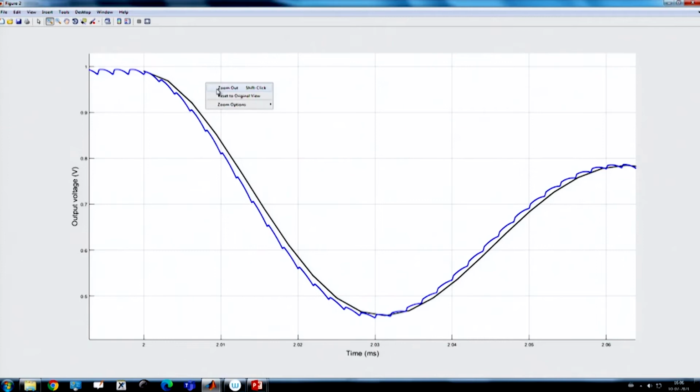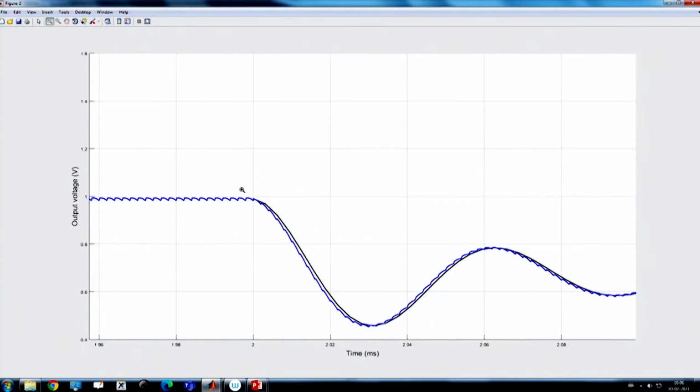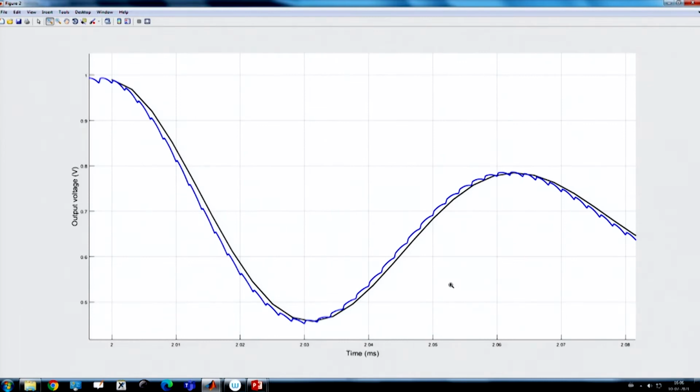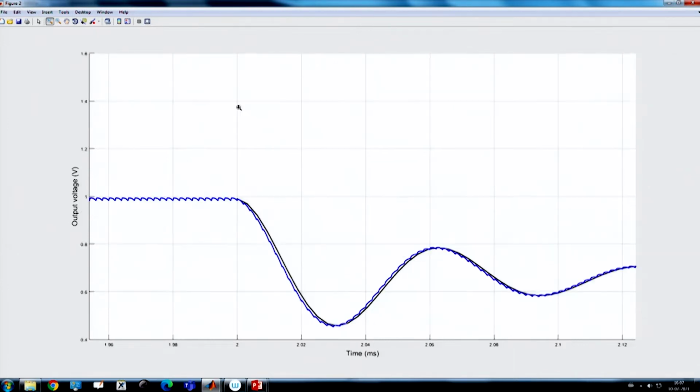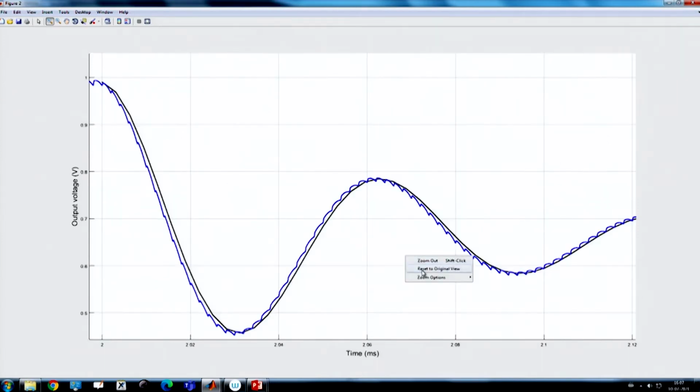The black trace indicates the response of the buck converter from the small signal model, and this model matching I will discuss in week 6 as well as week 7, so we do not have to consider it now. Here I am just showing. The blue trace indicates the switching converter, that means the buck converter output voltage when we have applied a supply transient of -4 volt, and you can see because it is an open loop converter.